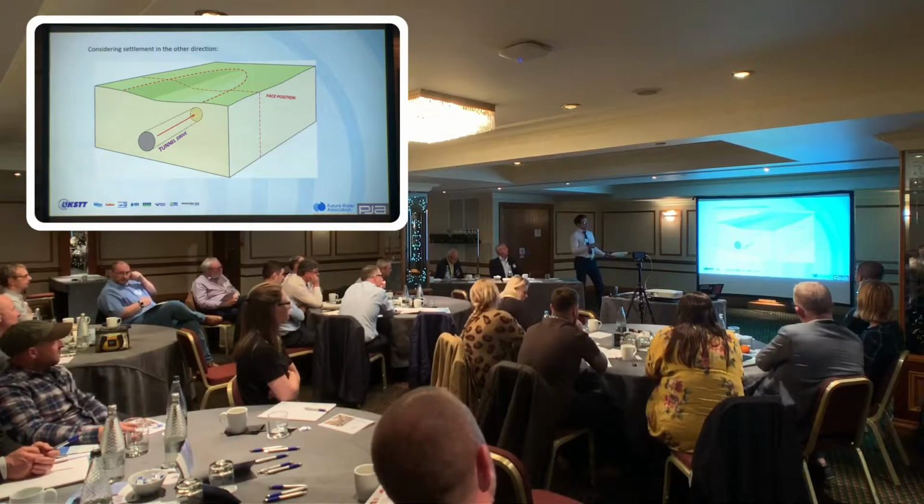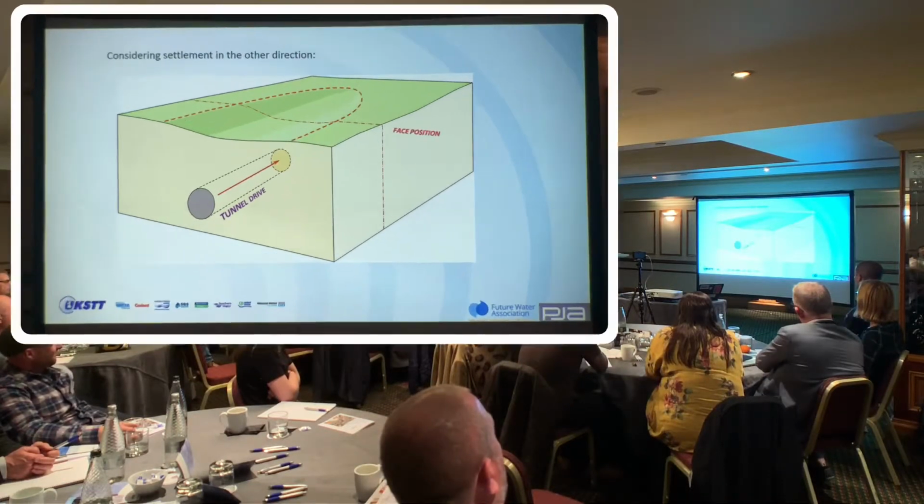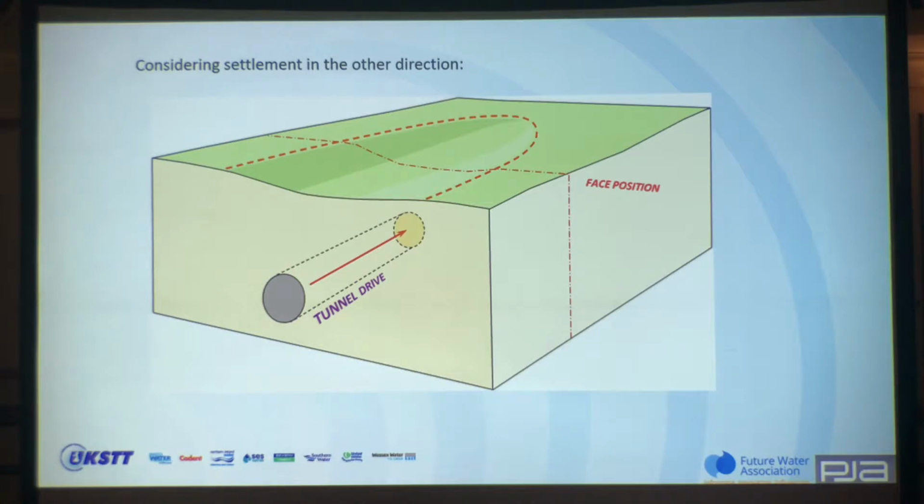And in some cases, you can be just outside those, so there's an option then to maybe take the drive a bit deeper, to give you a bit more overburden material, which will actually reduce the settlement or indeed widen the trough.